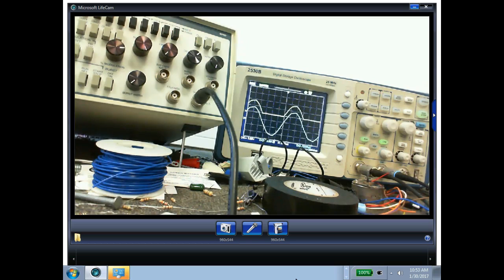Now, this would be one reason you would get an extremely low output, right? We would get 1/2 of what we expect. If I read 1/2 of what I expect, then that usually means one of your diodes is open. That's what I did. All I did was open up one of my diodes. Here comes that. There it is. Here, out. So all I did was open up a diode.